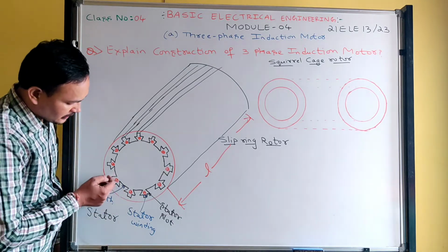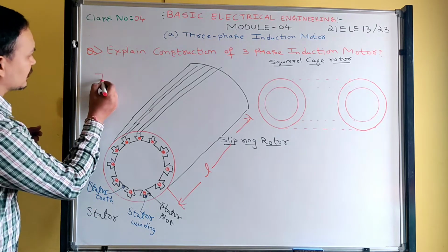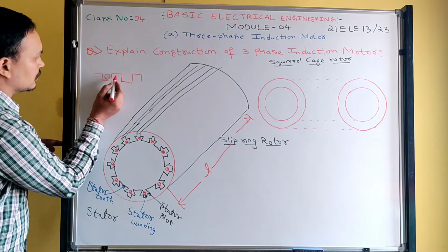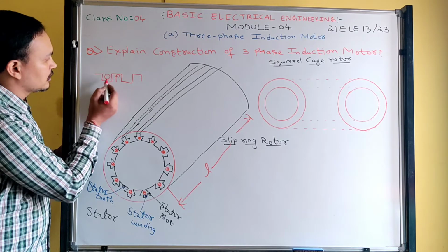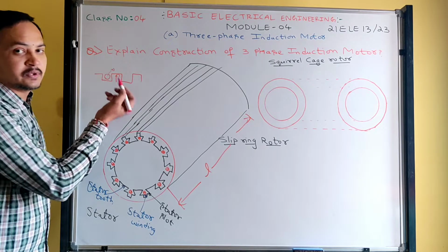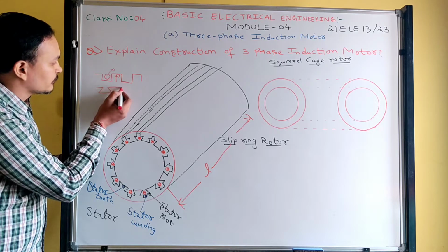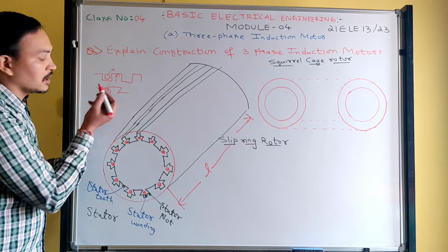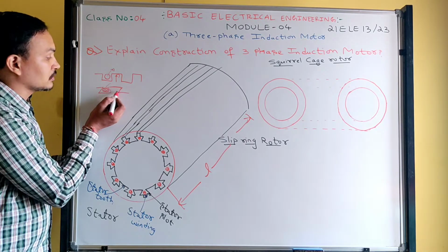So then about stator tooth, it provides a mechanical design balance. Okay, suppose if I made a slot like this, a parallel slot, okay, this is a slot and this will be the tooth. With this design, the conductor may come out of the slot easily. Suppose if I design like this, if I place a conductor here, this conductor will not come away. In order to make that, we have to design a tooth like this.